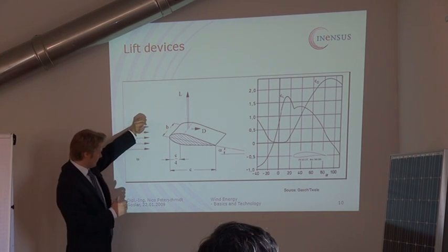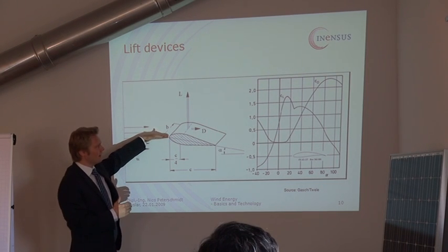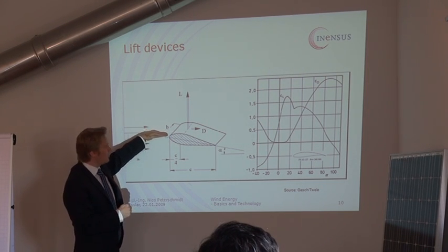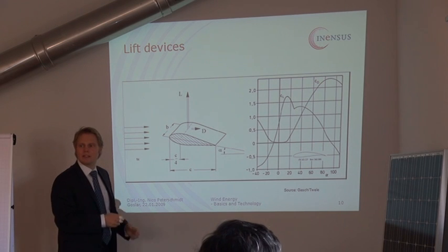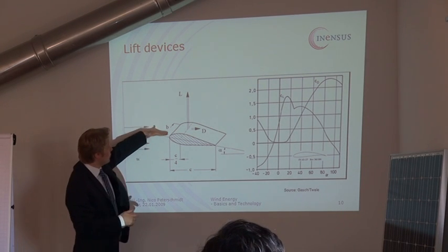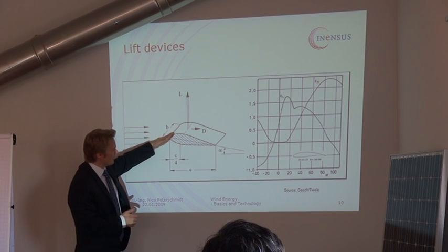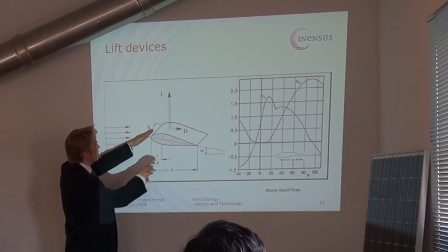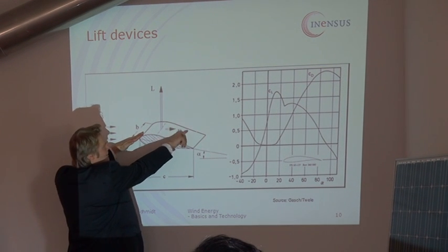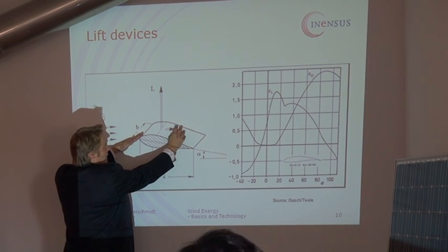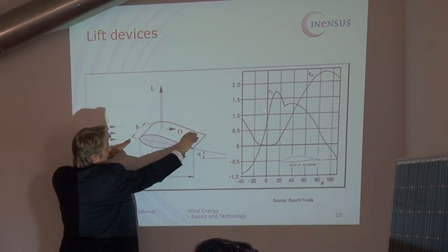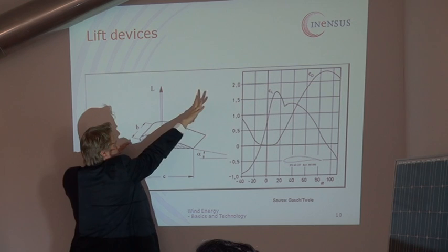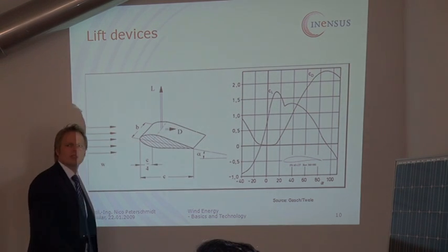And each blade has got one angle of attack which is optimal for the lifting force. If you decrease the angle, going in this direction, you will cause turbulence at the end of the blade, because the air flow goes around there and is not laminar anymore, and that is what we call stall effect.